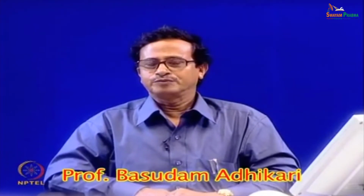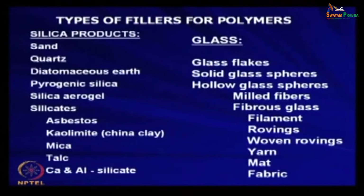Now, there are other types of fillers for polymers, such as wood based fillers, synthetic fillers or carbon based fillers. Silica based fillers are also available. Sand of fine particle size can also be used in the polymer as filler. Quartz, even if it is very hard, can also be used as filler for some products. Diatomaceous earth, pyrogenic silica, silica aerogel, then silicates and hydrated silicates are also used. Then asbestos, kaolinite, which is called china clay, mica in flake form and particle form, talcum powder, calcium and aluminum silicate are used as fillers.